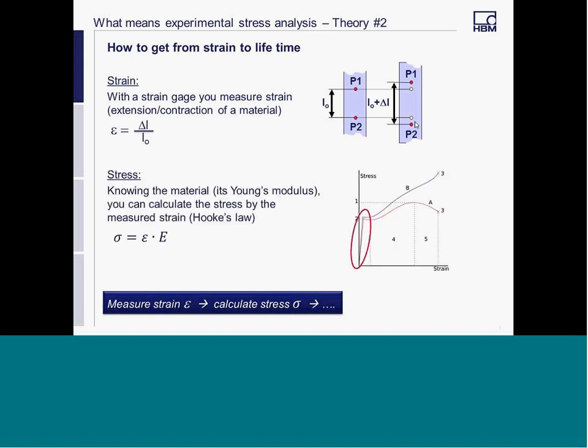Stress, as I mentioned before, these are the internal forces. There's an easy connection between strain and stress. This is defined by the Young's modulus, and that is a material-dependent figure. So there's an easy calculation. You just take the strain, multiply it with the Young's modulus, and then you have the stress.